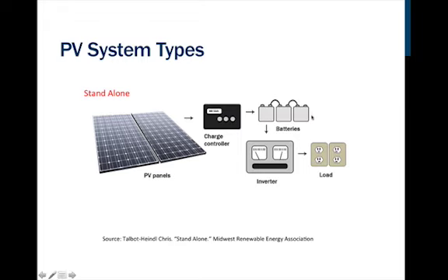The battery pack size is going to be larger. It's going to be large enough to support all of our electrical loads for 3 to 5 days without any sunlight. So this is going to be a very large battery pack. So the interaction with this system from a homeowner has just now shot up astronomically. So we're going to be constantly looking, 3, 4 times a day, at how much we're producing, how much we're consuming, what it looks like before I go to bed, what it looks like when I get up in the morning, so we can plan out our day and what loads we might want to run during a sunny day as opposed to multiple cloudy days.